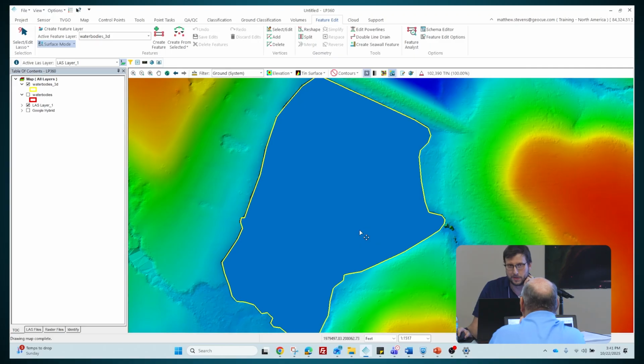That's a very good question. Because I used such an exaggerated buffer, it didn't matter in this scenario. But let's say you're making a really tight buffer, like I think on page 128, we say typically 1/4 to 1/2 the nominal point spacing, but you want a minimum distance of 1/4 of a foot or 1 foot. So if you did a buffer of 1/4 of a foot or a foot, and you moved it more than that, you're right. You'd have to redo that buffer classification for that to turn out correct. That's exactly right. That's a good point. But because we use such a massive exaggerated value, we're never going to have that issue.